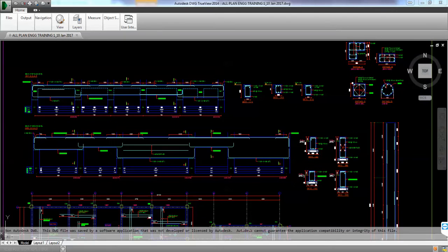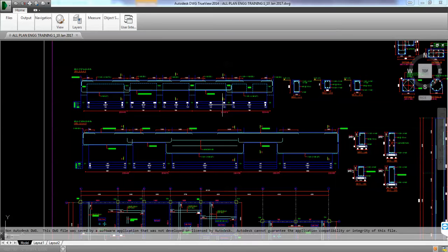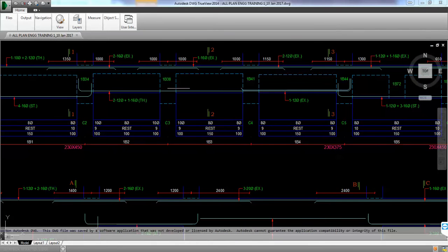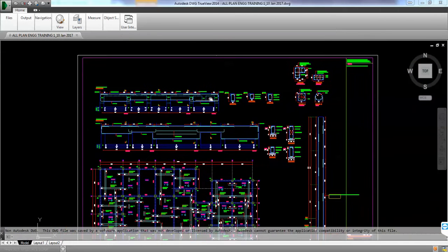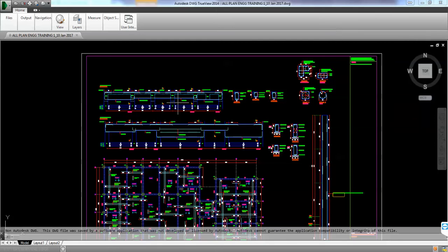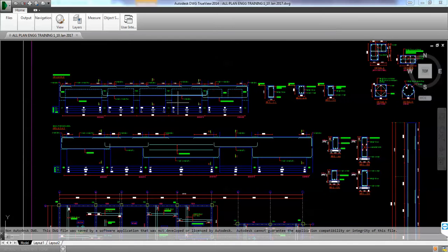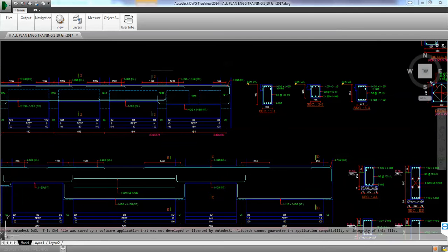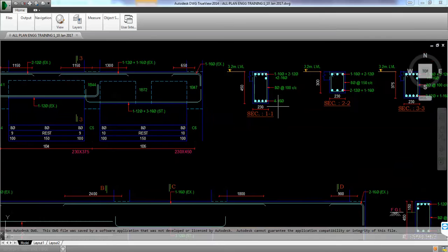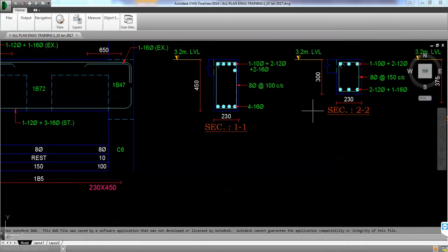Normally in 2D, once you finish this drawing, you can do a copy and then extend the beam, do some stretches and modifications, and you just update the rebars, the marks, and the bending schedules, and it gives you the impression that it takes less time. The problem is you have little control over the 3D model, so once you get modifications, you can get stuck with some errors, because if you are distracted while adapting this detailed beam to another, you might forget to replace some rebars.